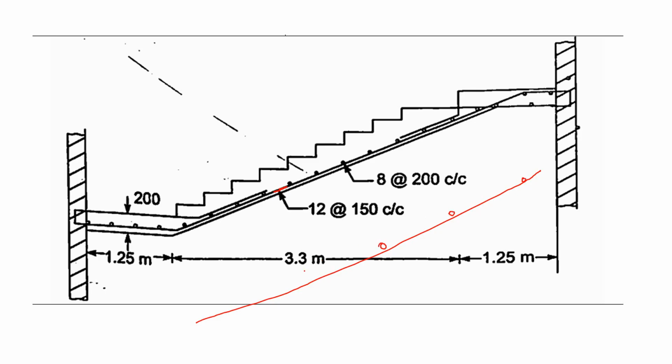This bar is the 8 mm bar at 200 millimeter center to center. And similarly here, if you see, this landing slab is provided with the 8 mm bars. So here you are providing the 8 mm bar. So this is how we give the reinforcement detailing.